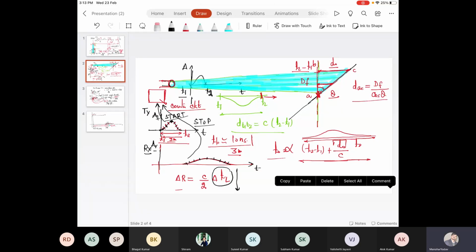So in the previous lecture, we discussed how the trigger signals are generated to send a command to the counter circuit to start the counting and to stop the counting. Here, as you can see, this is the energy pulse generated by the laser transmitter. It's a zero value, then it attains its peak, then again comes back to the zero. At which particular time we trigger, that trigger signal is generated for the counter to start the counting.